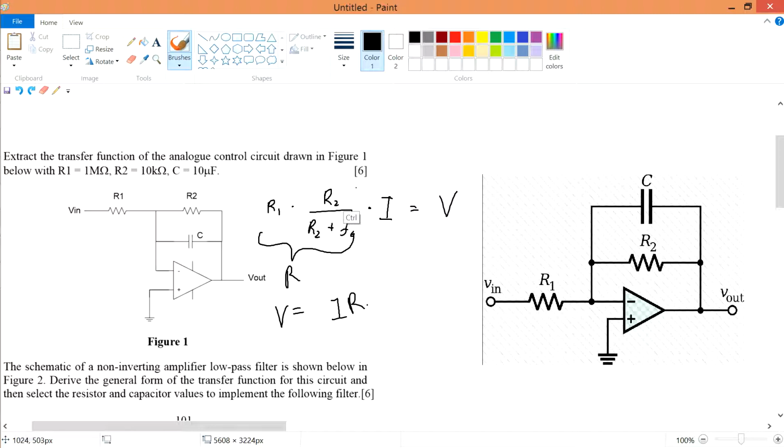So you're going to solve for all this, and eventually you can come out with an equation to represent it. This thing over here, if you think about it, looks a bit similar to K A over, if I bring this FC to the other side, something like S plus A. Your R2 is somewhat your resistance, and your FC is controlled by 1 over 2 pi FC, your frequency. Frequency is talking about j omega, so at least you can see the link now. This is your transfer function, multiplied by your current. Your current is your input.